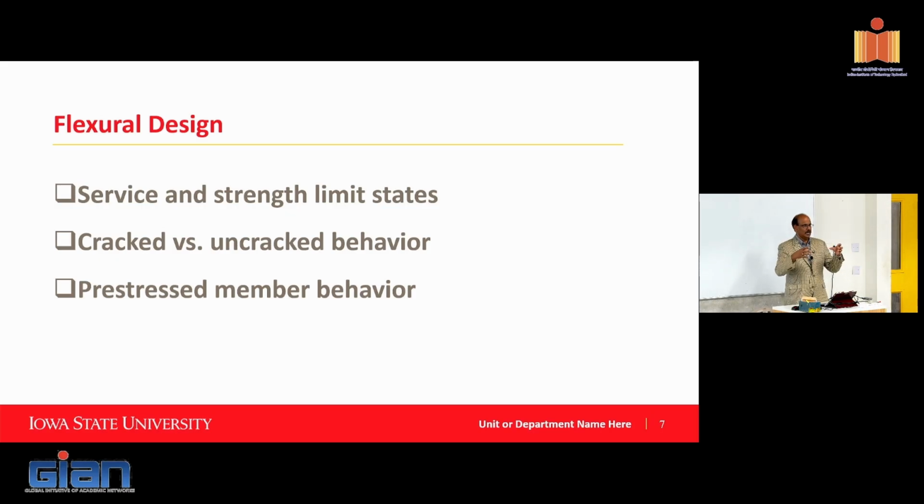Casting it, I think I probably used the term handling it, which is how do you pick up the thing and store it? Would you pick it from two ends? If you pick it from two ends, will it cause cracking? So in those cases, they may have a spreader beam and pick up the slab using four points. So those things have to be looked at. You don't want to cause any cracking at all.